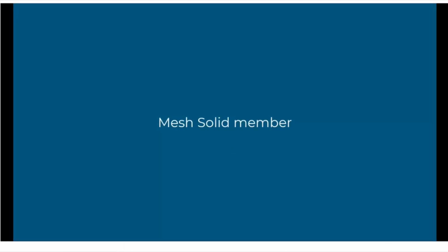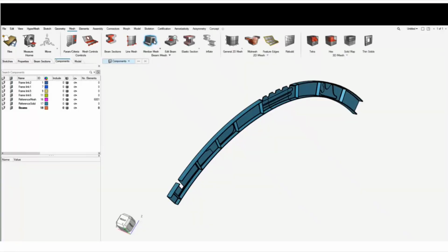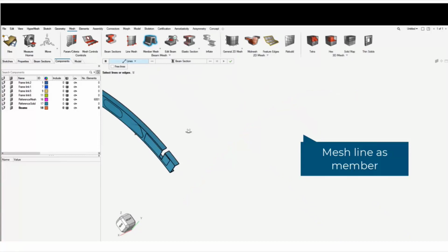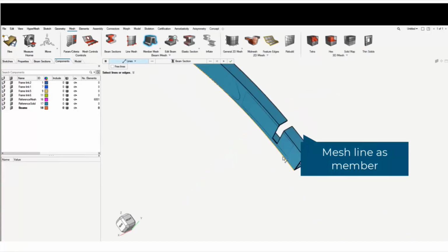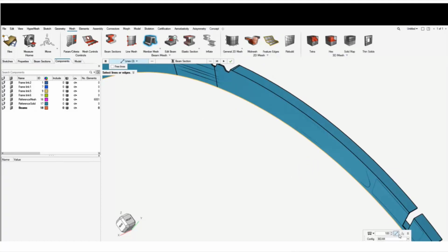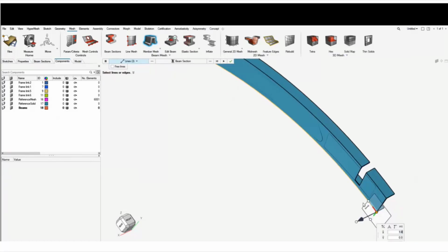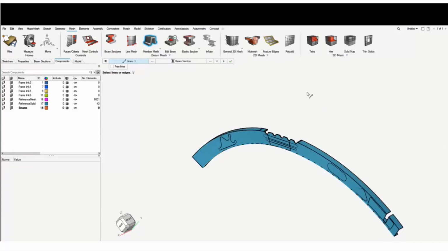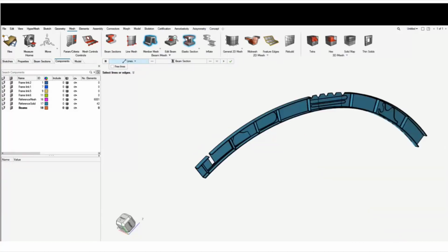As a first example of model reduction, while easy, I will go with a solid frame, and I want to reduce that solid onto an equivalent 1D. So I will simply sample some 1D elements as member elements along the beam, providing a size of 100.